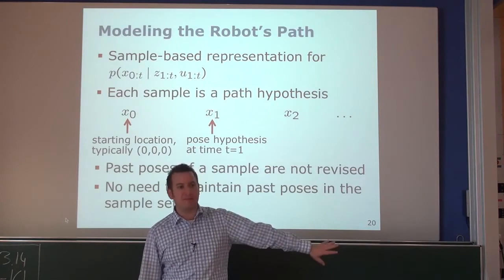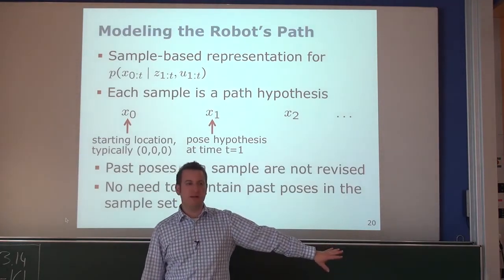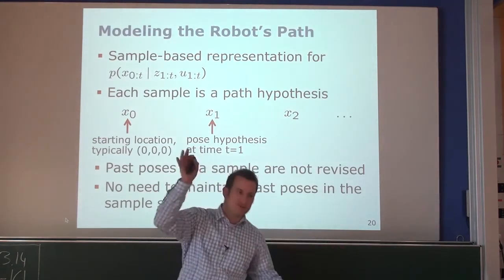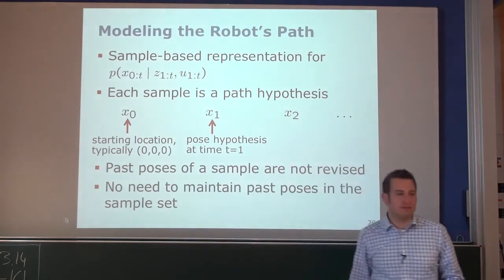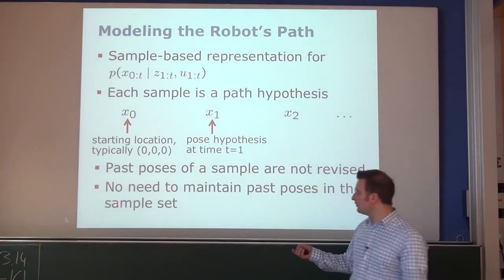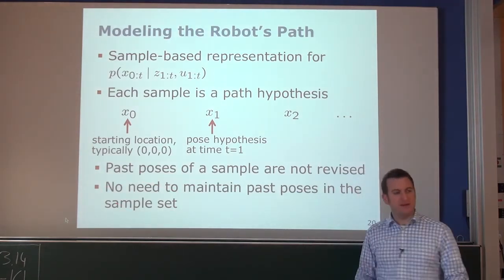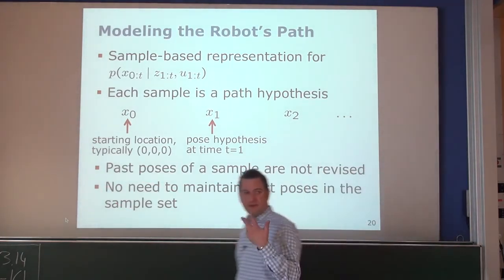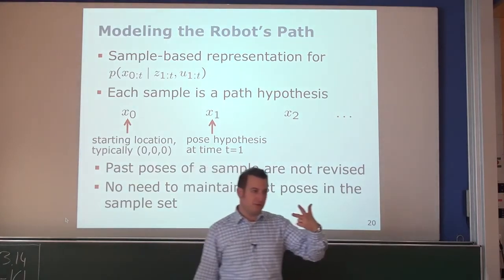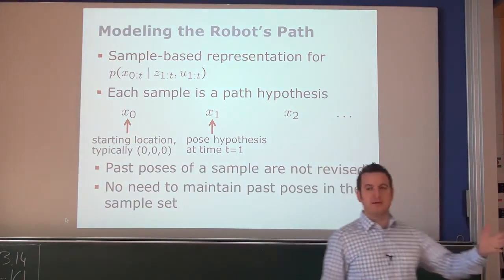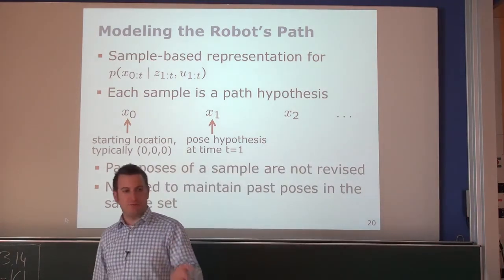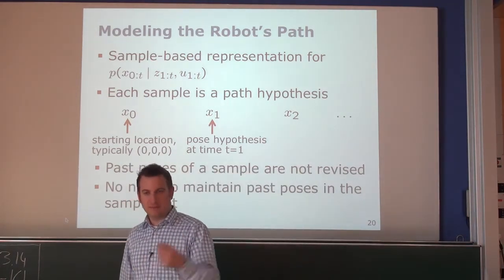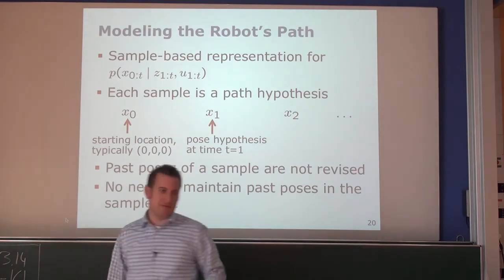I could, in theory, let's say, dump them somewhere to disk in case I need it. Typically, implementations do that because they want to draw the trajectory in the end. But for the mapping process itself, I don't need that for the estimation problem I'm facing here. So in practice, every particle only needs to maintain 3 dimensions for the pose and then 2 times m dimensions for the landmarks, where every landmark is a 2x2 Kalman filter.